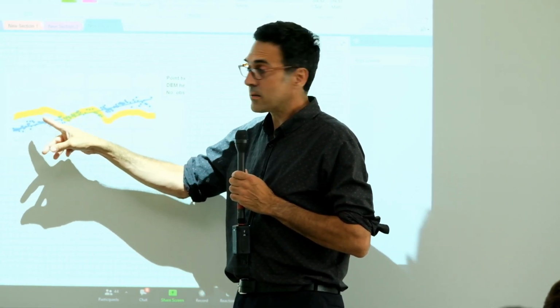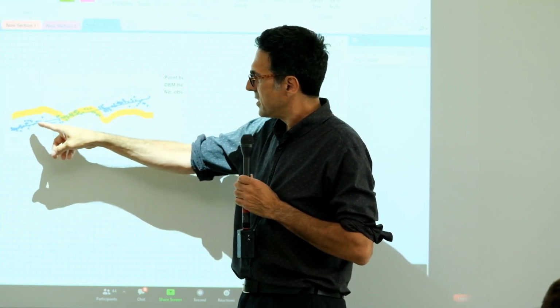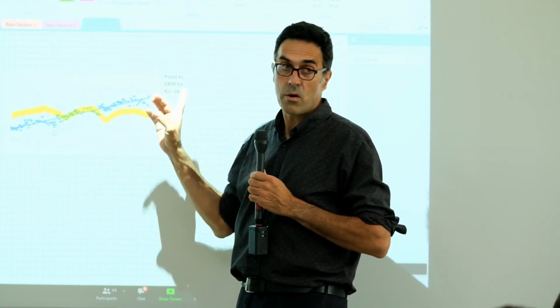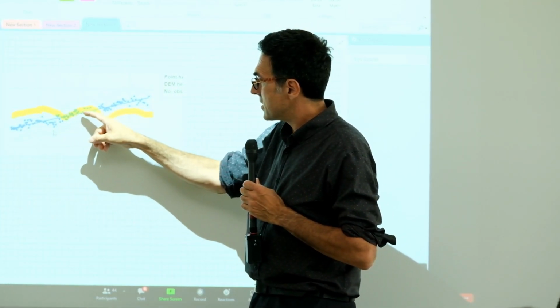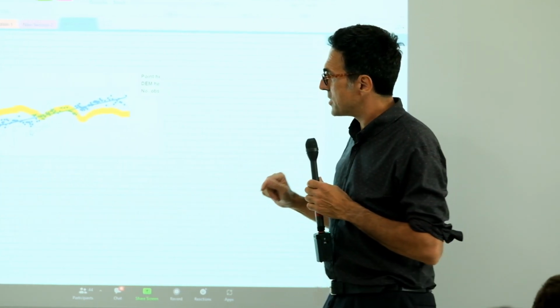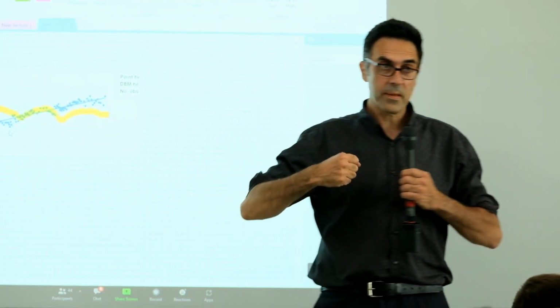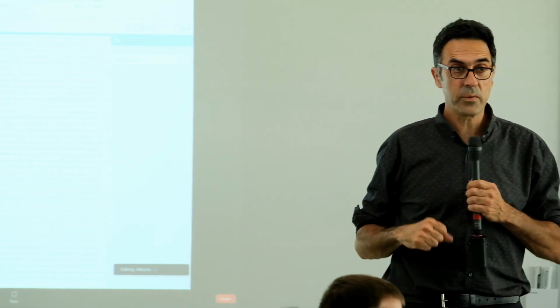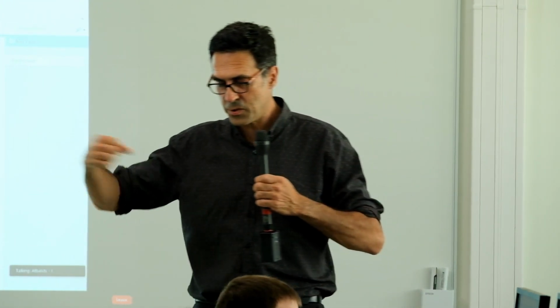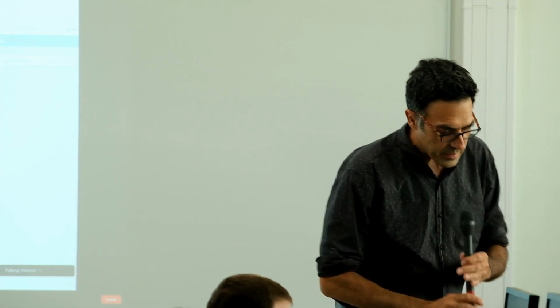Most likely here, at this particular point of the bridge, the blue line is the wrong interpretation. Most likely it is this kind of pattern, and this matches with what we would expect for thermal expansion in summer and winter. Right? So basically this is a long bridge, steel construction. So in summer it's warmer, the bridge goes out, so this point goes to the left and this point goes to the right. And we can check that.